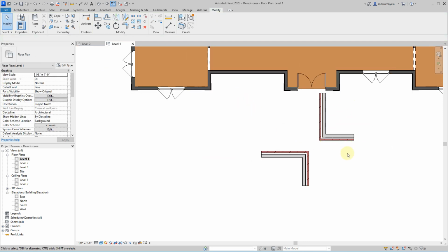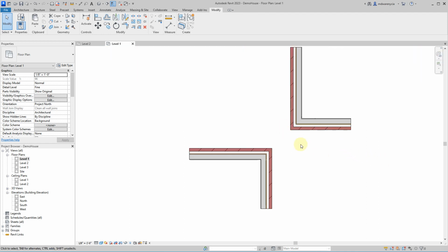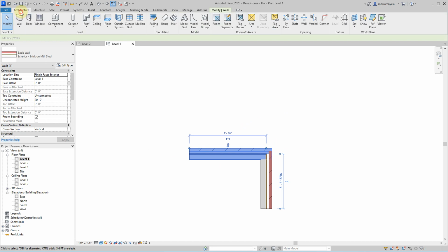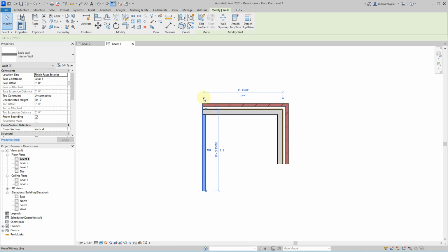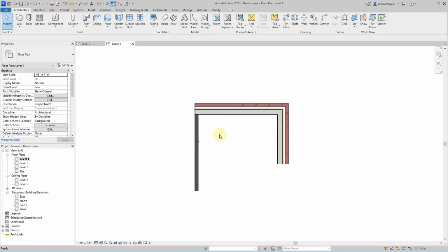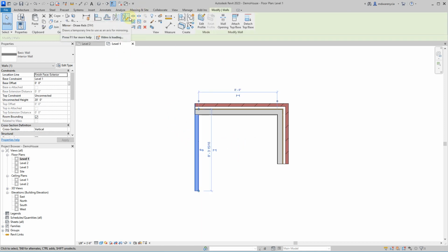So again, it's one of those ones where it's like, well, because this just kind of placed it out here. And so I don't find a lot of uses for that because typically I'm going, okay, well, I know I'm drawing these walls here, so I know what a specific dimension is, so I'm not going to just willy nilly place the walls because now I've got to go move them again, right? So if I know I need this space to be 8 feet, well, then I'll just make that 8 feet, right? I don't know. It's one of those tools that I don't use because it doesn't seem to come in handy for my workflow often.